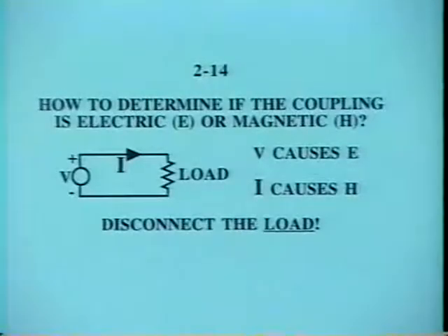There's a very good way to diagnose a problem by using this approach. Let's switch over and use this for a moment. This is the power cord going to my scope over here on the side. Let's say what I notice, when the scope is turned on and the power cord is energized, is that when I move this power cord near a piece of equipment, let's say equipment sitting down below me here, the noise level increases.